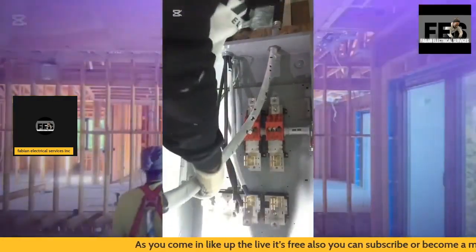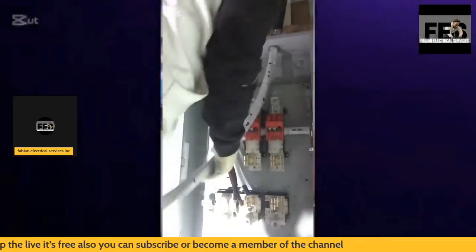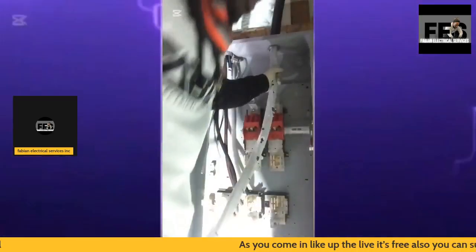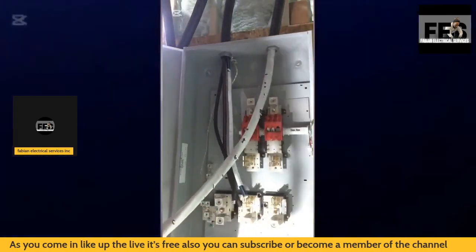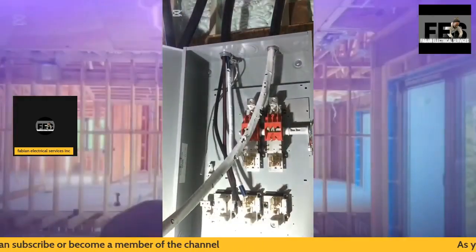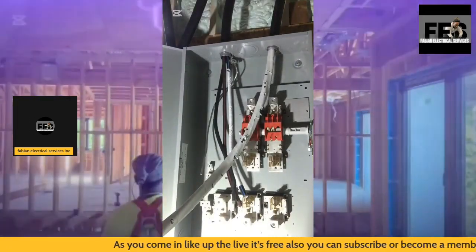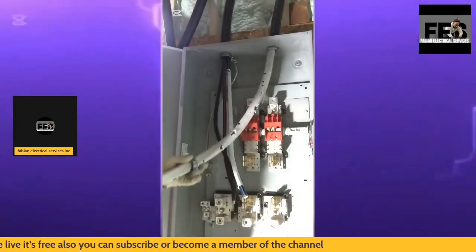Again, the electrical conduit that I'm using is going to be AC conductor. We call it Teck cable, and there are parallel runs being run from the outdoor meter base. Again, what I like to do with an installation like this is make sure that I keep that white sheeting on. Once I land my conductors inside of the panel, I'm going to remove that white sheeting.